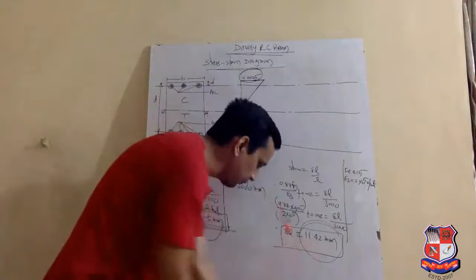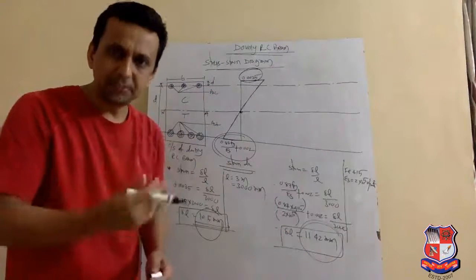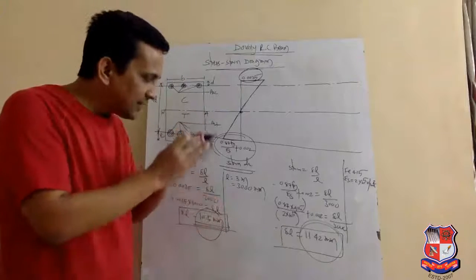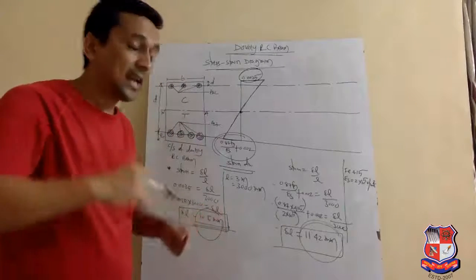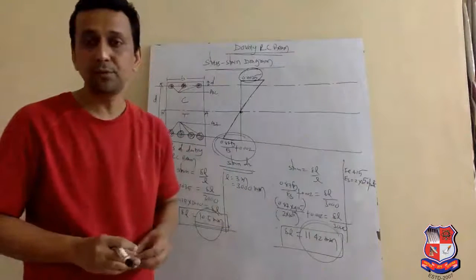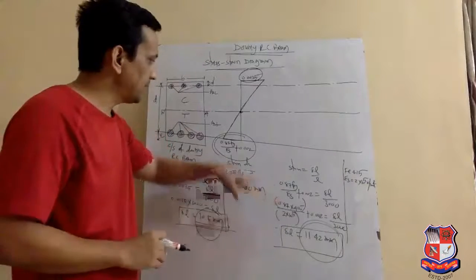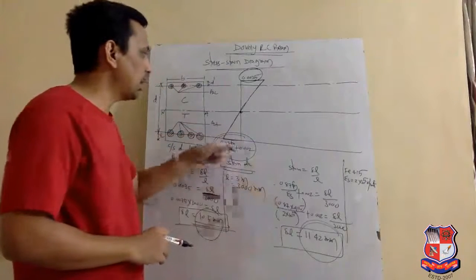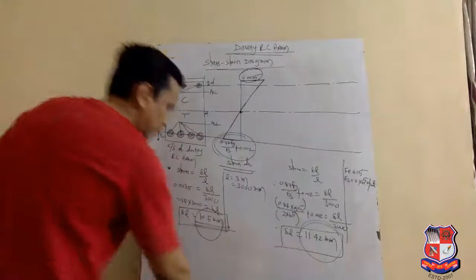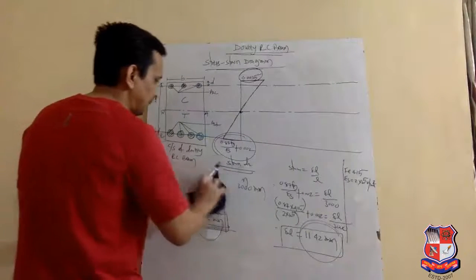Now, what does 11.42 mean? It means when the beam is subjected to some load, and due to that load the tensile deformation in the tensile reinforcement goes beyond 11.42 mm, it will fail in tension. So this is the simplest explanation of strain in the form of deformation. Now we are going towards the stress diagram.